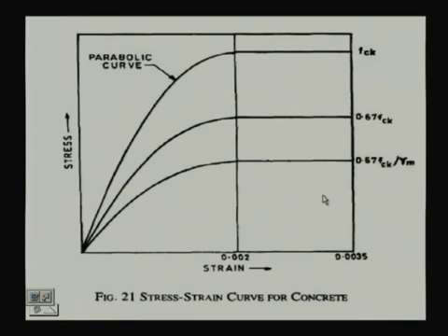For our design purposes, we are taking this curve, and when we take the actual design value, we shall consider this curve, which is based on the curve we are getting from the experimental data. Then we are taking 2/3 of that. Further, we are dividing by the partial safety factor for materials, and then finally we shall get the curve for our design purpose.